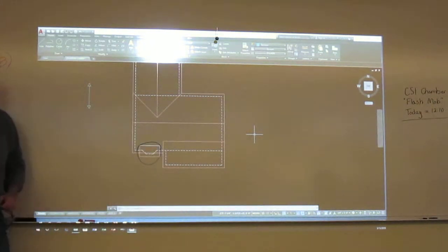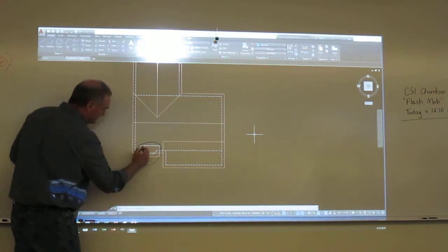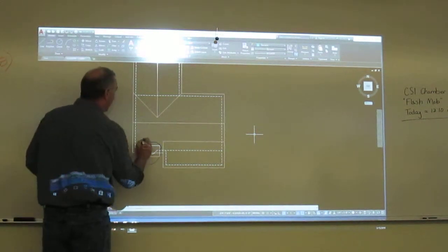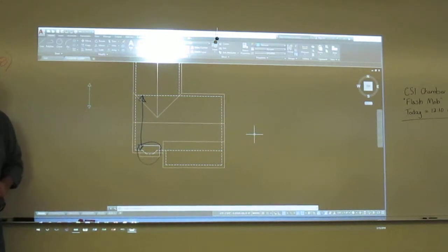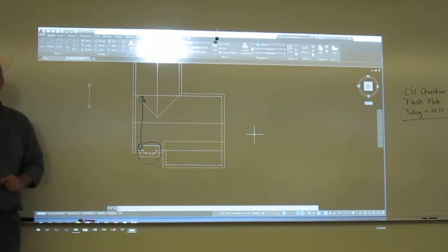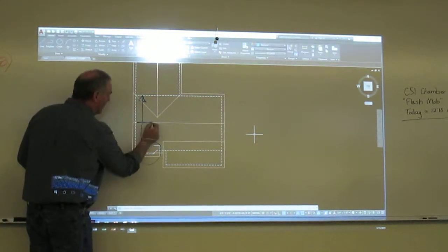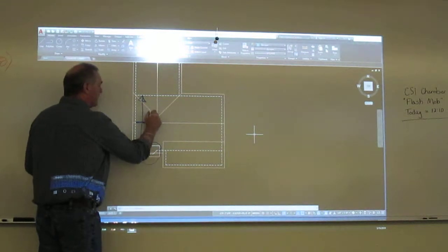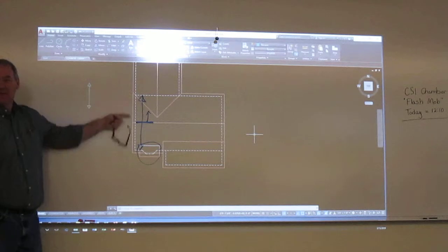Now also, you need to look at the underside of the roof, what's going on there. On this area, I've got a truss that's going to run from here to here. But is it all straight or is it all vaulted? It's both, right? Somewhere about right here, that closet and bathroom and everything takes over, and I want that to have a flat ceiling.